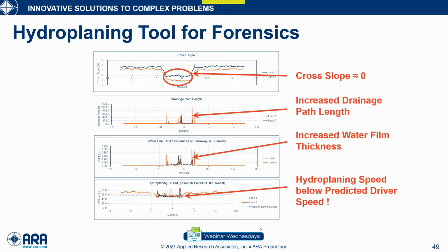So the enhancement didn't represent any enhancement on the existing models, but only on the tool itself. So you may argue that you should be using a different equation for asphalt concrete than for PCC pavement. Or you could even say that you need a different equation for open graded and another for dense graded, but these are the limitations that the tool has so far.